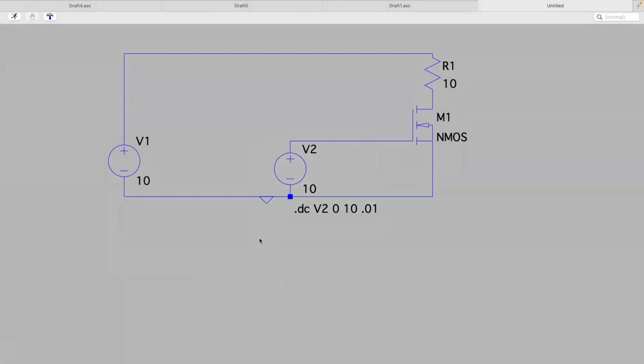Some PCB. I don't think you guys are going to design PCBs in this class, but you will eventually. Some general good practice: don't put your ground at another node. It makes it difficult to discern if you meant to do that or not. And in some programs, it actually becomes really difficult to tell if they're hooked up or not. So always try to keep one node slightly away from ground.